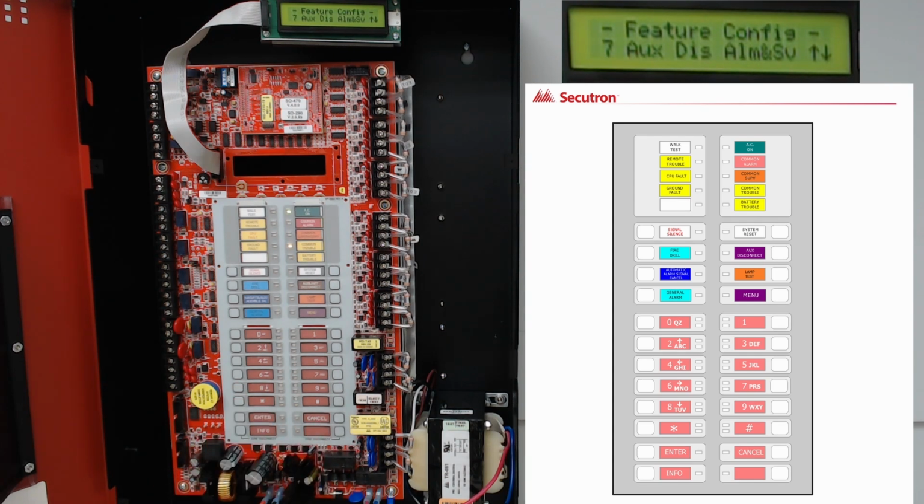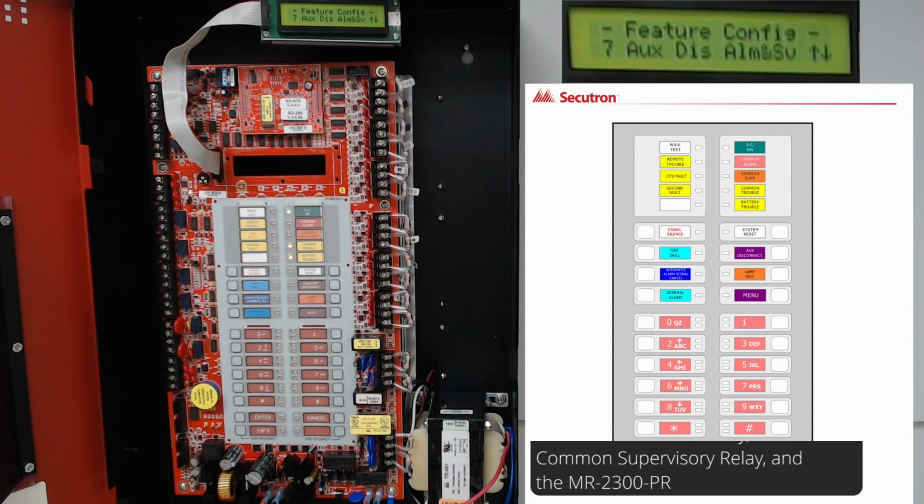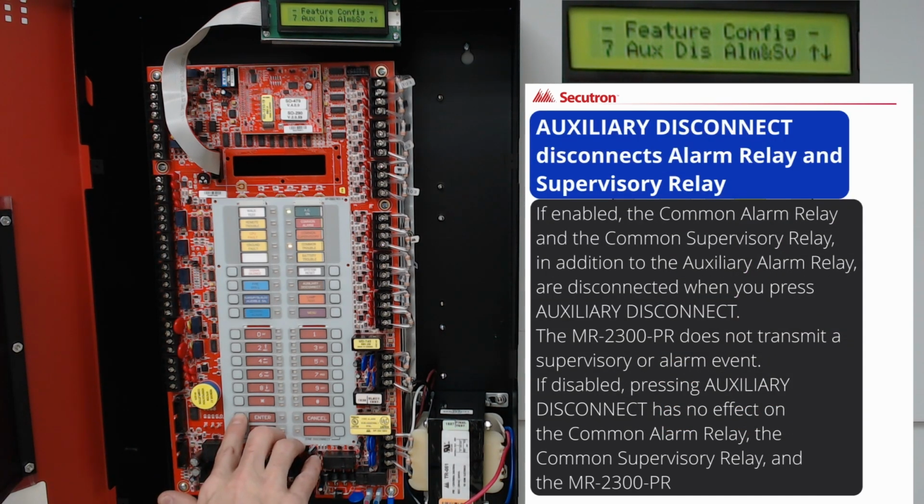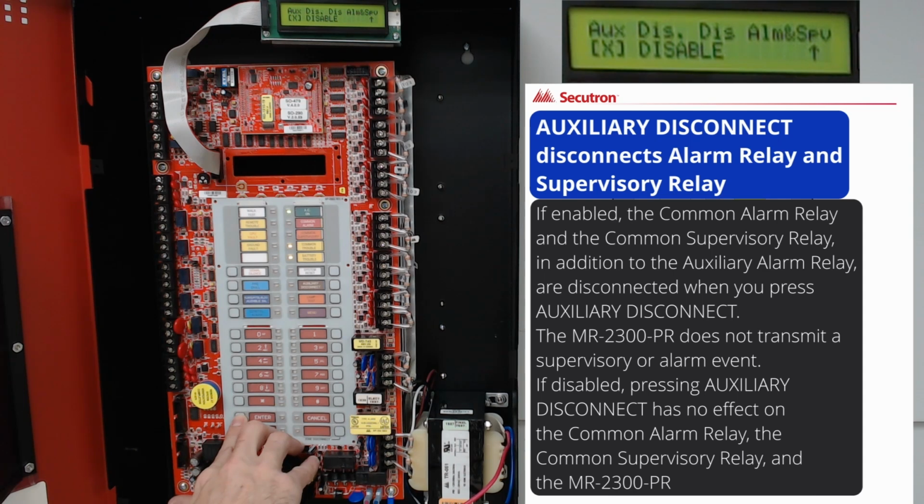Our next option is Auxiliary Disconnect, which disconnects the alarm relay and supervisory relays. When we enter into this, the option is disabled by default. By pressing the up cursor arrow and then the left or right cursors, we can enable the aux disconnect.